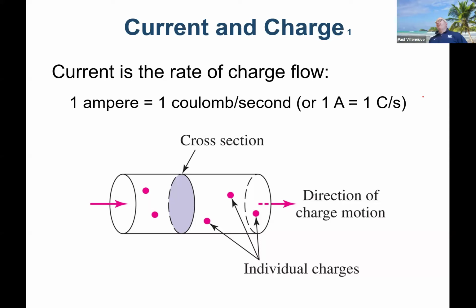Electricity is not like sharp edges. If you've ever walked into a substation, you don't see square things having current or voltage anywhere near them, because it'll start to bleed electrons through the air. It'll go around, and then you'll actually get corrosion. Essentially, it will delete the material. So almost all current carrying devices either are circular or will have round edges. Even insulators tend to have round edges because you're trying to reduce the corona effect.